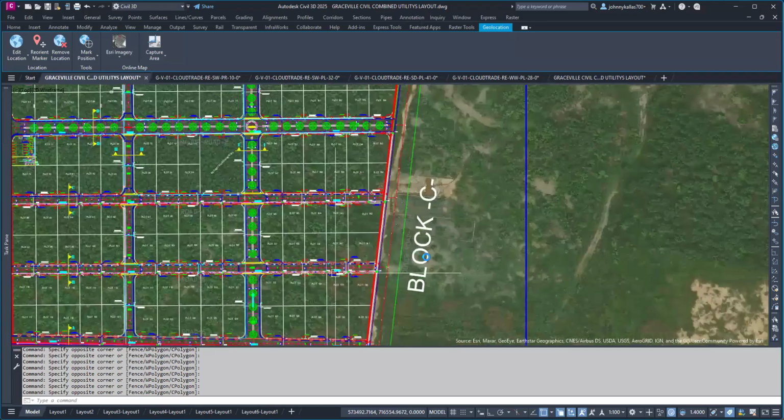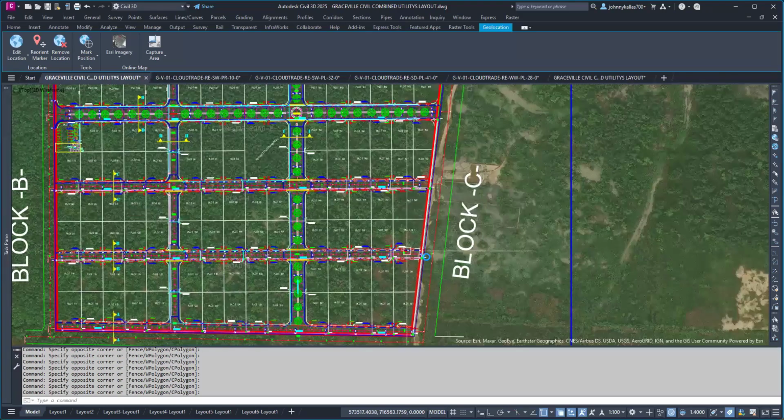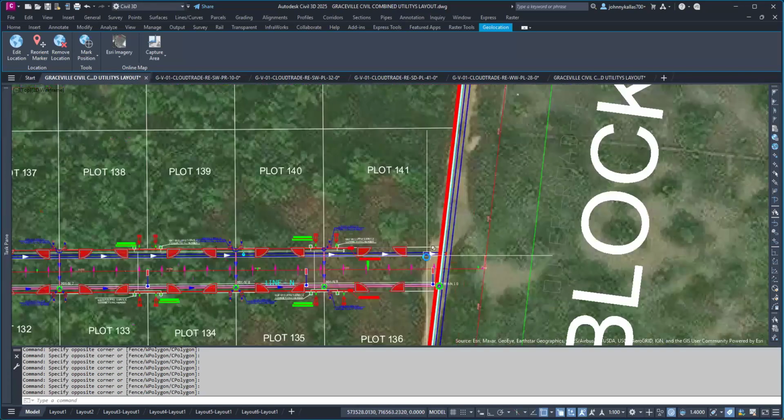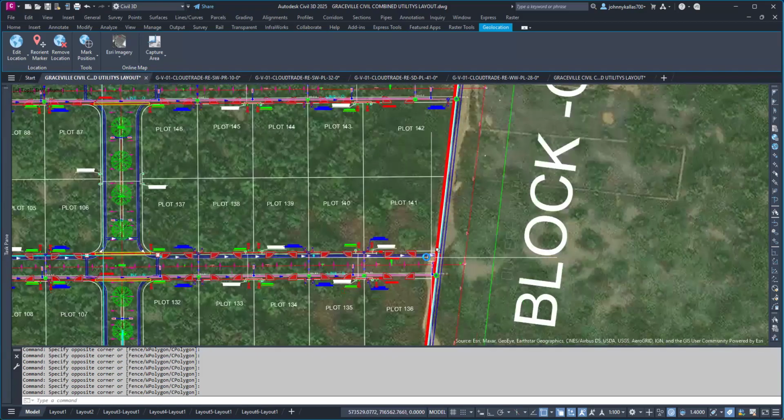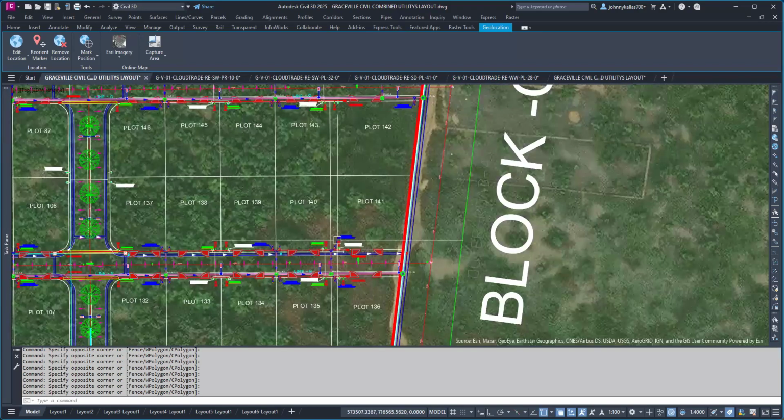For example, if you want to pump to this road, we will build at the edge of the road a bound wall. Then we will pump inside the bound wall. Then a dozer and excavator. The dozer will push the sand and the excavator will level it. You get me? So the sand will not go outside, will not enter inside the plot. Only the water. The density of the sand is bigger than the density of the water. So the sand will settle and the water can go by gravity.